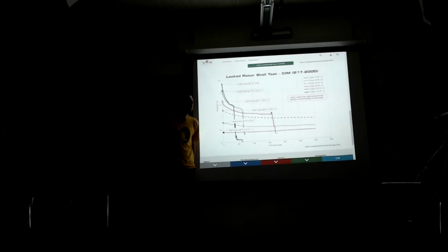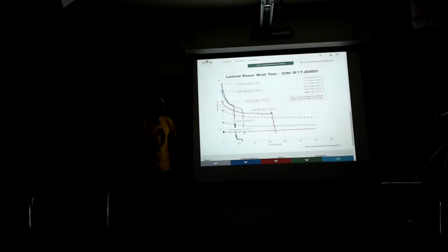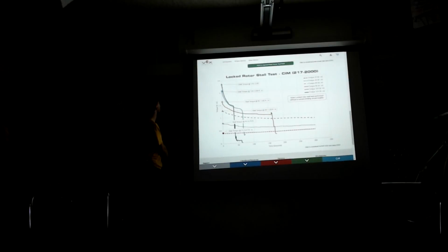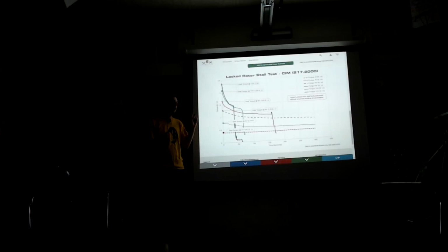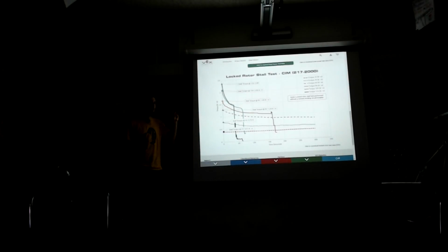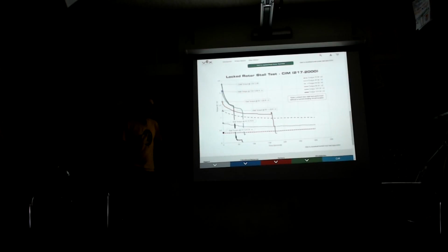And how about multiple motors on one motor, like on a drivetrain or something? You just multiply the torque. You can make a super motor where you add the torques together, or you could actually do it in your free body diagram, but you're going to get the same result. It doesn't matter if the motors are oriented in parallel or on the same side? It would just all add together. It comes down to your free body diagram. If you have 2 things applying a torque to another gear, and the torques add together, then it's equivalent to adding, no matter which way the motors are pointed.